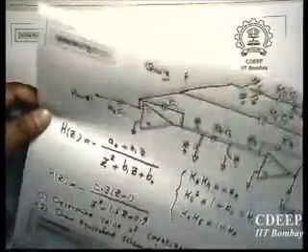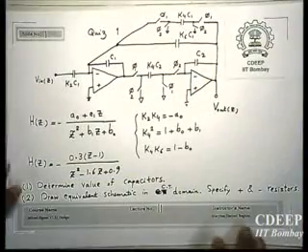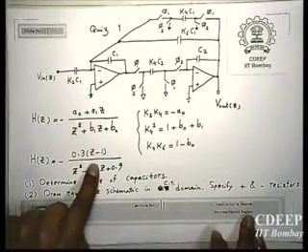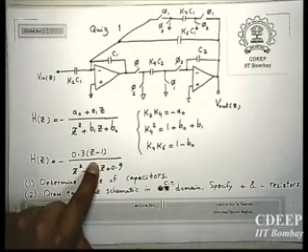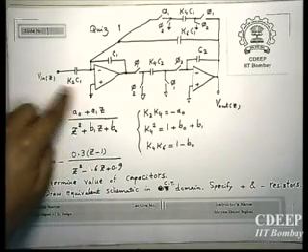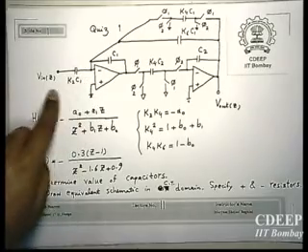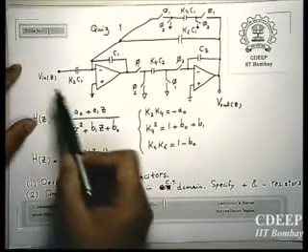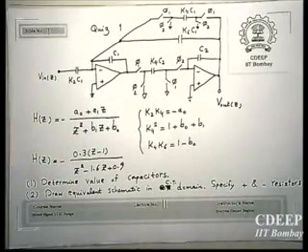I just simplified one of the examples of the Ken Martin book. It's the same thing. I simplified, removed two capacitors. As you notice, we have only Z equal to 1, which is equivalent to S equal to 0, right? So therefore, two capacitors have been removed from the input. That's why you don't see those two. There is a 0 at S equal to 0. That's it. It's a bandpass filter.